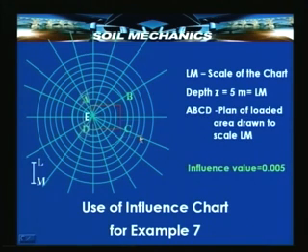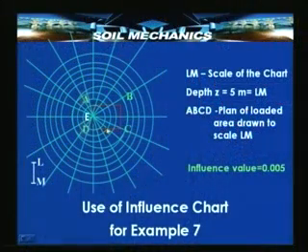After drawing this rectangle to scale on a transparent sheet of paper and then superimposing it over this diagram in such a way that the point of interest lies exactly at the center, we can get the influence factor, the total influence factor corresponding to the whole area. The sum of all the elemental areas which come here is the one which corresponds to the total influence factor. So, we need to compute, means we need to calculate and count each one of these elemental areas.